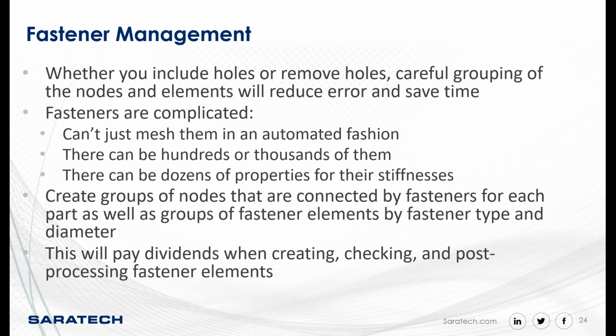Whether you include holes or remove holes, careful grouping of the nodes and elements will reduce error and save time. Fasteners are frankly complicated. You can't just mesh them in an automated fashion. You just can't push a button and create fasteners. You can have hundreds and thousands of them, and they can all have different stiffnesses.